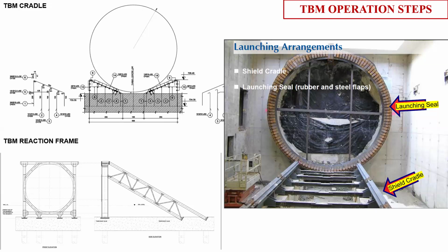In Calcutta Metro, our shaft was a crossover structure. We are crossing the trains there, so our shaft is a permanent one. In Lucknow Metro, we did not prepare any separate shaft. What we did was launch from the station itself. The shaft that we prepared was a part of the station. We prepared half of the shaft and then expanded it later. So it depends on the purpose of the structure.